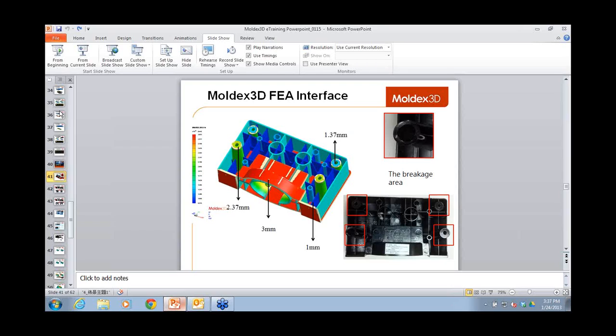And during assembly, the breakage chances for the mounting holes, which are these guys here, which are also called bosses, increases. And therefore, this project aimed to leverage Moldex3D's FEA interface to get the material parameters, and then we used Abaqus to simulate the locking torque process. And through the simulation, we can obtain the best results to increase the part's strength and improve the part quality.